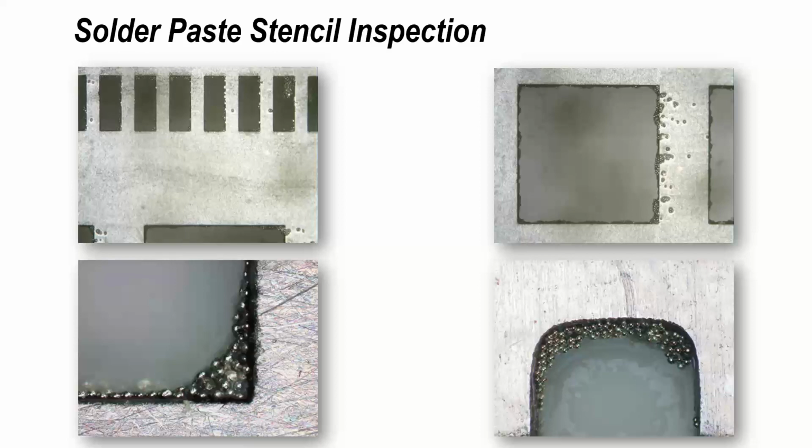Now, if you print and you don't get 100% release on a stencil during the printing process, then this may be dislodged onto your next print, and you might get a perfect print. But if these are stencils which have come out of your cleaning rack, your library of stencils, then this is bad practice, because those particles have probably got no flux left in them, and you're possibly adding solder paste volume to a joint when you print, and you might have an issue with the amount of flux available to reflow that volume of paste. That's a possibility.